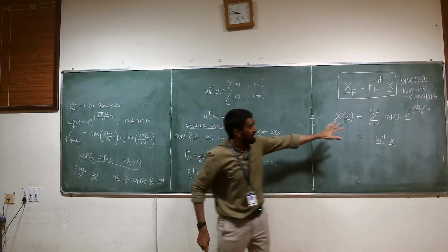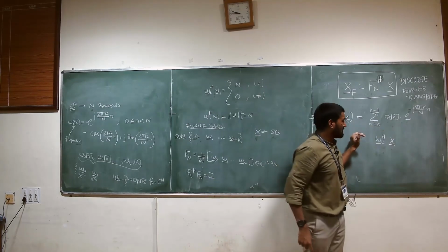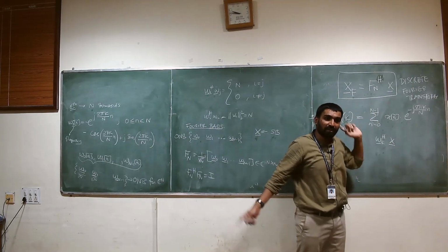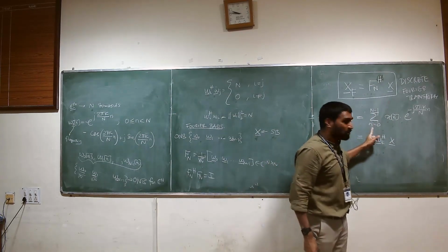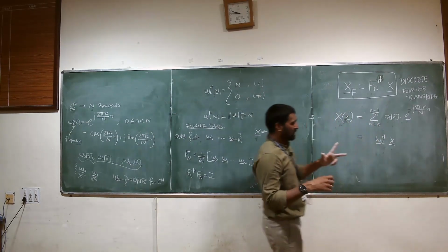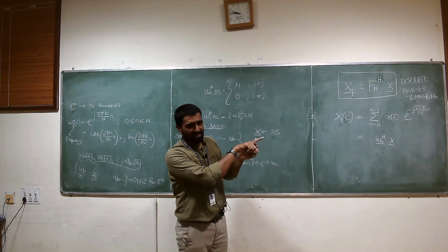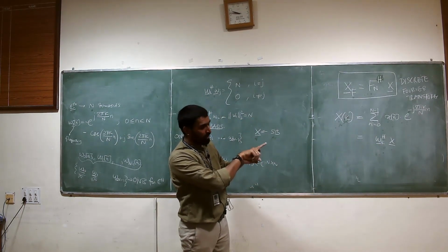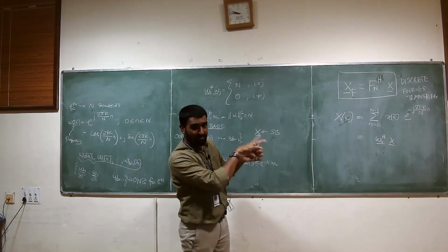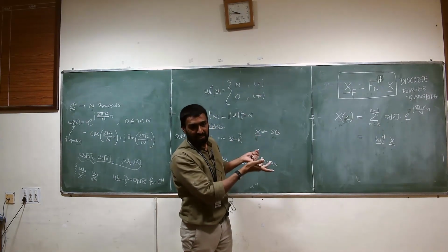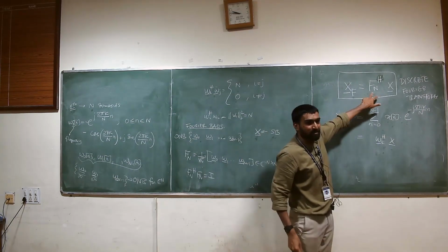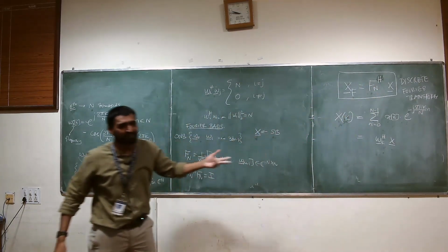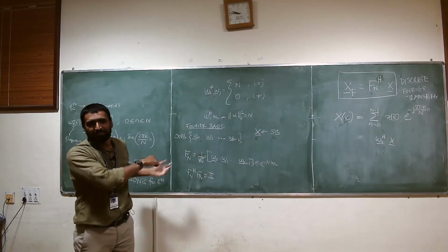Maybe this is how at least it's covered in undergraduate DSP. But now you have a different way of looking at this. Your time domain signal is some vector in this Cn space. All you're doing now is looking at the same signal using a different basis. That's basically your Fourier basis. So it's a representation of the same signal, but with a slightly different reference.